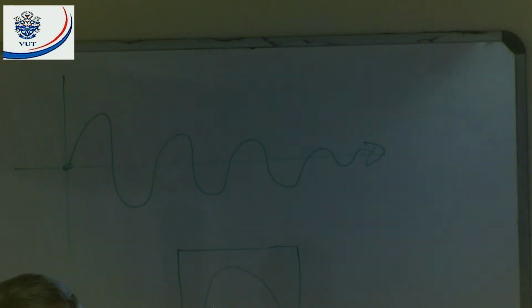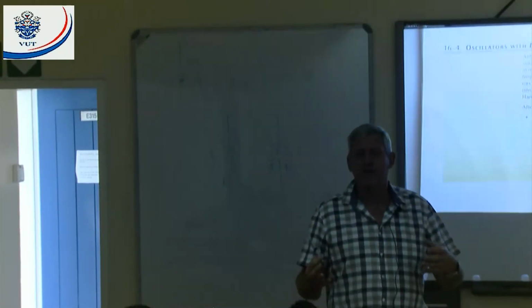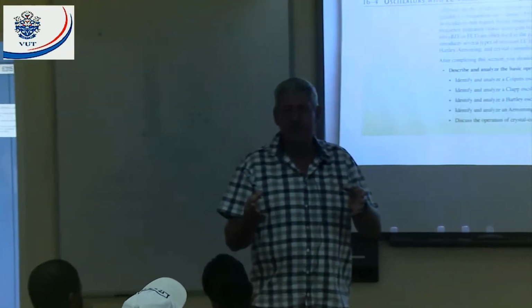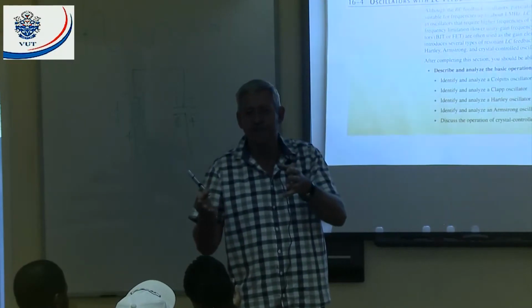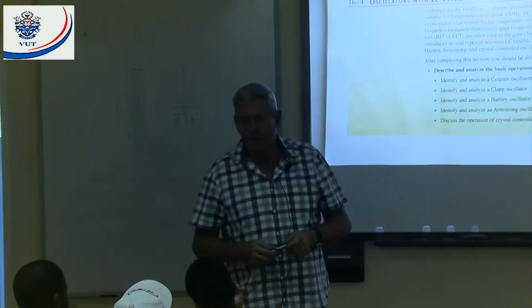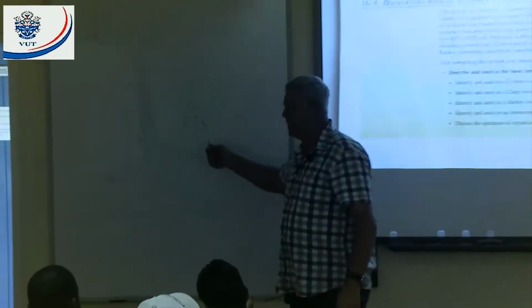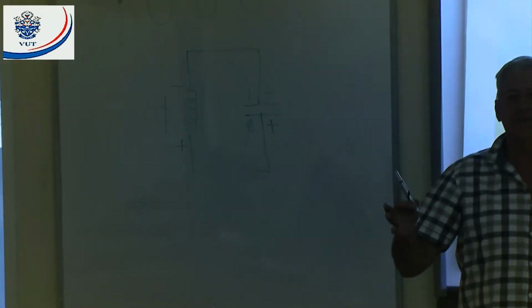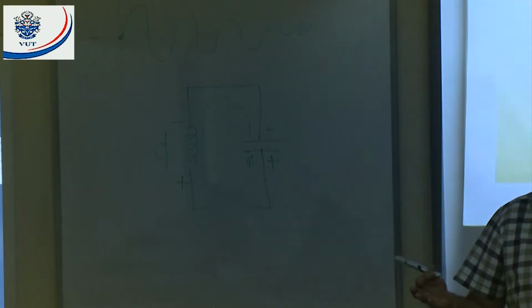All right. Now, all these oscillators we're going to do in this part of the chapter are LC oscillators. How do they work? They have an LC resonance circuit connected to an amplifier. All right. What's the purpose of the amplifier? To just overcome the losses. All right. That means if you have to study it, go and look at all the different feedback circuits and, you know, an amplifier. All right. Very simple.